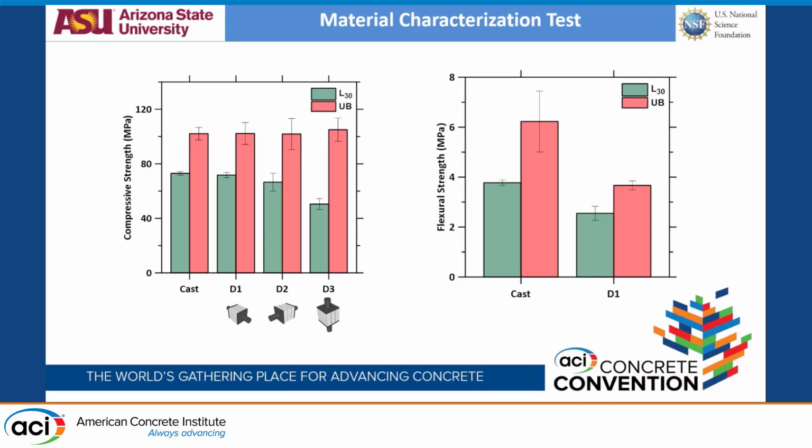As the auger that we have extrudes, it rotates the mix, and if you have seen a thick kind of UHPC mix, you will see that once it's stirred, it looks like water, while once it's setting, it looks like solid. So technically, let's say you are printing filaments side by side.